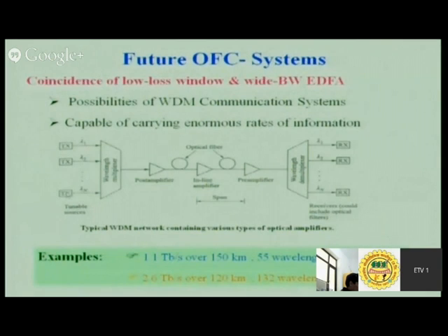We will discuss it at a later stage in detail. So it will be put over the same fiber, and in between we need the amplifier, we need other engineering systems to transport the data, and at the end again I need a wavelength division demultiplexer. I have to separate the different wavelengths. So these wavelengths can be provided to different users. This is the technology which is only possible in optical fiber. So as a result, it is a very high capacity WDM network.